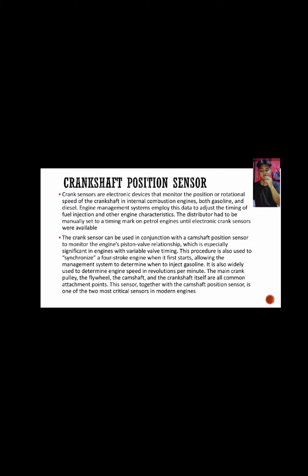This procedure is also used to synchronize a four-stroke engine with its first starts, allowing the management system to determine when to inject gasoline. It is also widely used to determine engine speed and revolutions per minute. The main crank pulley, the flywheel, and the crankshaft itself are all common attachment points. Together with the camshaft position sensor, it is one of the two most critical sensors in modern engines.